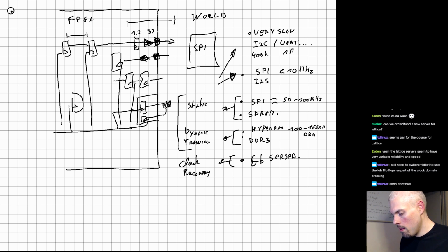But this distribution here, we're just gonna ignore, because the FPGA has global networks that ensure that the skew is relatively small. In the iCE40, even the official tools actually ignore it for the most part, because the FPGA is so small and the global network does a pretty good job. Now, in a larger FPGA, like a large Kintex 7 or something, then you can actually have substantial skew, of like 1-2 nanoseconds between different points in the FPGA of where the clock arrives.